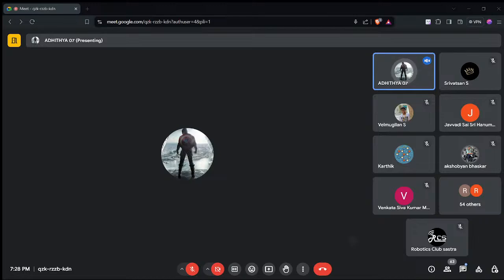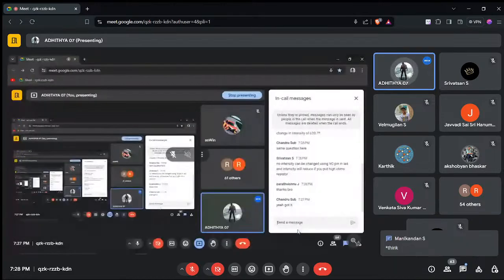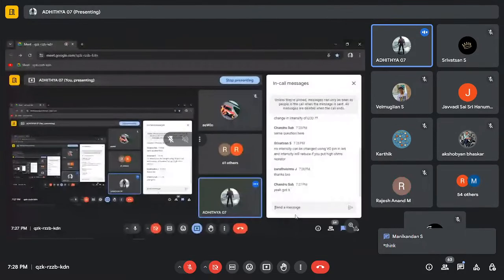To do this, we have a motor driver. It does not give initial power to start. So it moves from 0 to 12, right? It controls the power of the motor, more or less. As I was saying, the motor moves from 0 to 12, but the Uno can only provide 0 to 5. We need a mediator so that it can scale that 0 to 5 to 0 to 12. That is a motor driver.